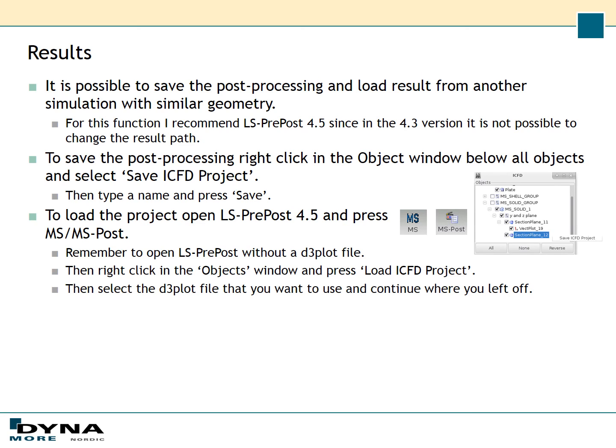For cases where you have a more complicated geometry and you have created several objects to view the results, you may want to save the post-processing, and that is available in PrePost, but for this I recommend to use the beta version of LS-PrePost 4.5, since in the 4.3 version the result location is hard-coded in the saved file, but in 4.5 you can load a result from another simulation but with a similar geometry.